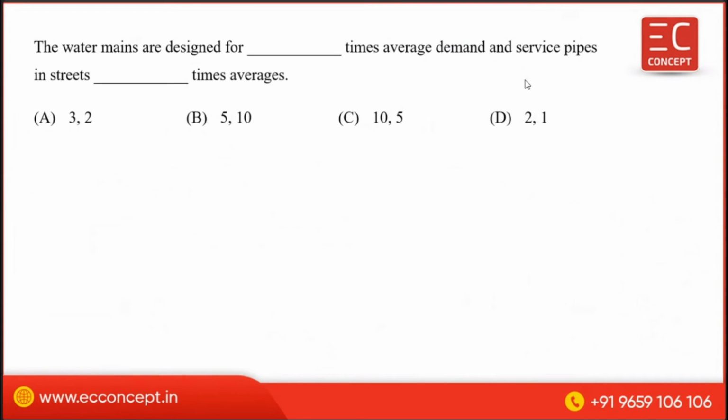The water mains are designed based upon the Indian standard. Okay, 3 times the average demand, and the service line in the street is designed for 2 times the average.